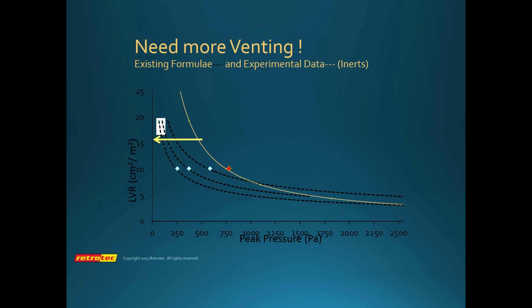And what I found out was most of the data was taken at the same leak to volume ratio, as if they did the same test over and over and over, and the data was not taken over a wide range of enclosure leakage in order to find out what the shape of the curve is, which is why we have the curve shapes incorrect for most of the manufacturers. And they're slowly kind of catching on to this, and I would say pretty much all the major manufacturers in North America now have accepted the FSSA curves as being correct because they've been well documented against experimental data.